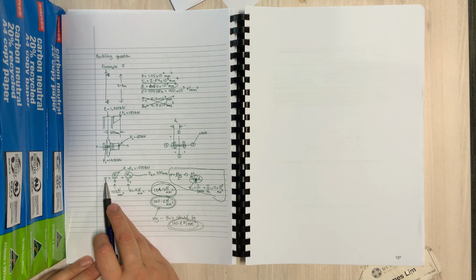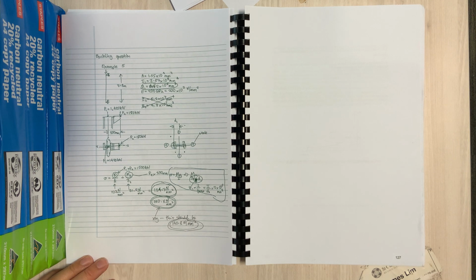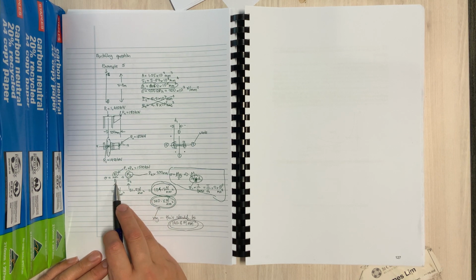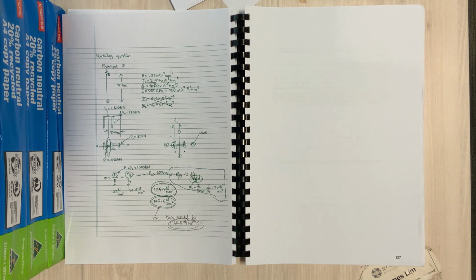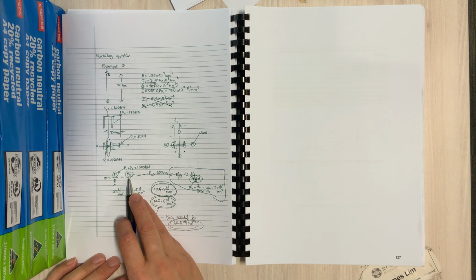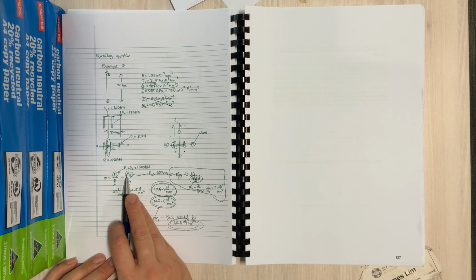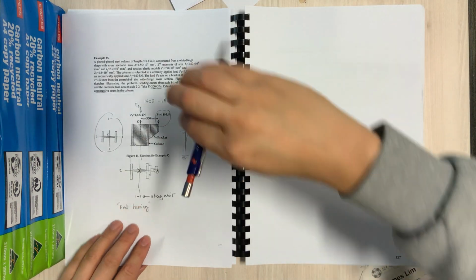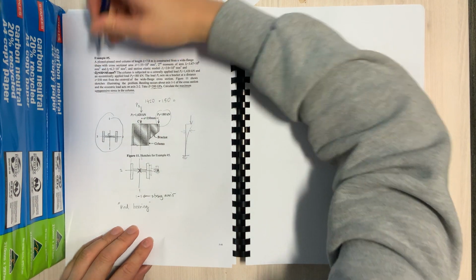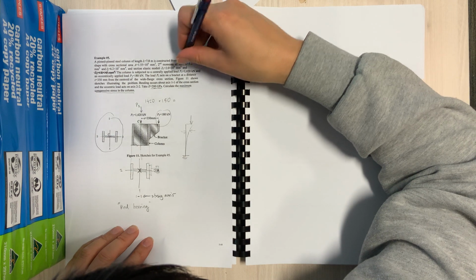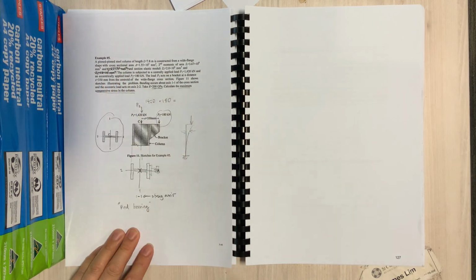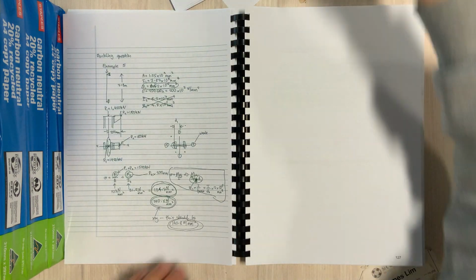So the stress is going to be your force over area. That's going to be the axial component of the stress, which you will get by P1 plus P2 divided by the area, and that would turn out to be 103. And onto that you need to add your bending component, made up of the bending moment divided by Z1. So that again goes back to what I said was the red herring. The red herring is perhaps the Z2 information and the minor axis information, which is actually not needed in order to solve the problem.